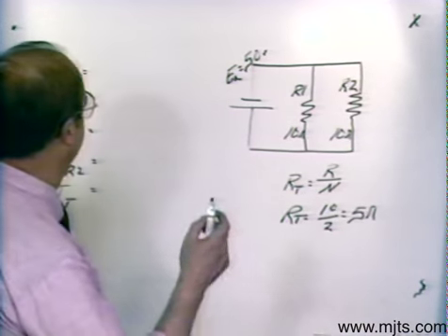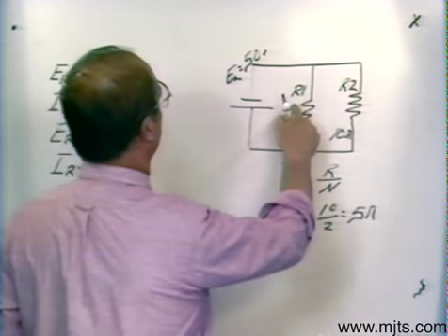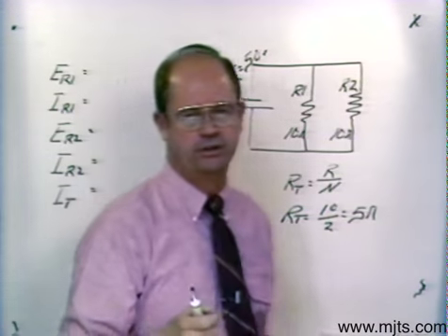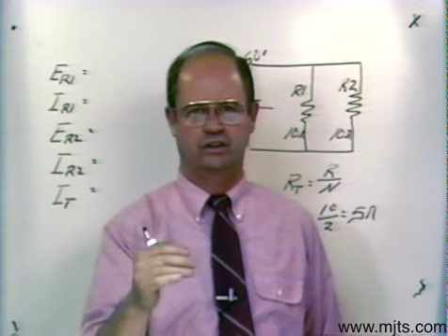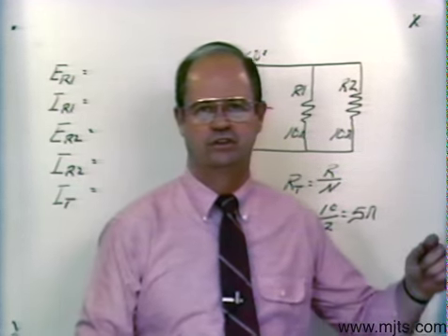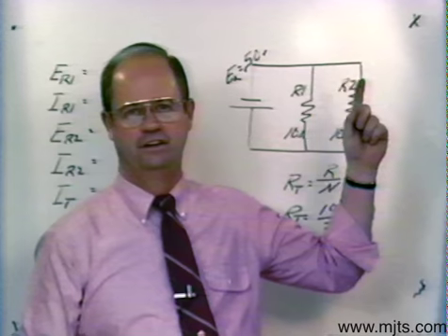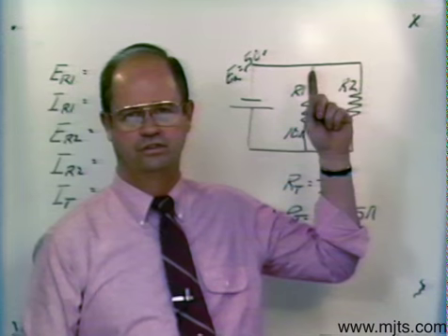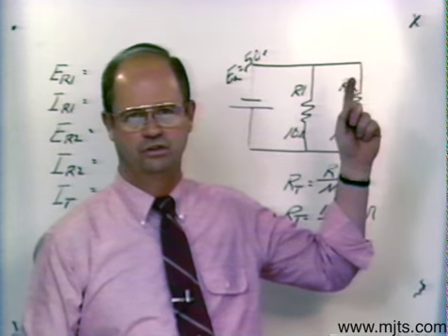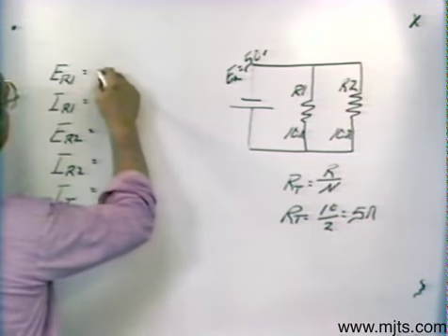Okay? Now we're being asked for the voltage across resistor 1. That's pretty easy if you understand how we treat each of the parameters. We know in a parallel circuit that the voltage drops on those resistors are both the same. In other words, if I've got 50 volts for a total, I'm going to have a voltage of 50 across each one of those resistors for a parameter. So let's just put 50 over here.